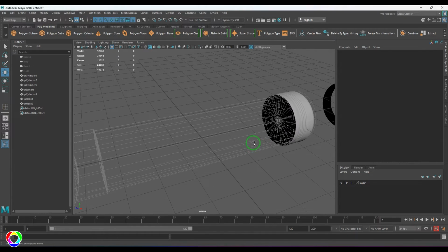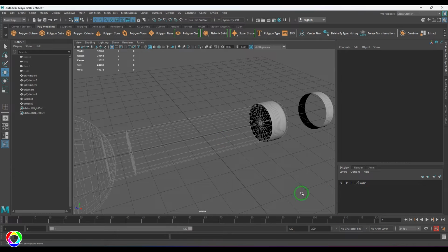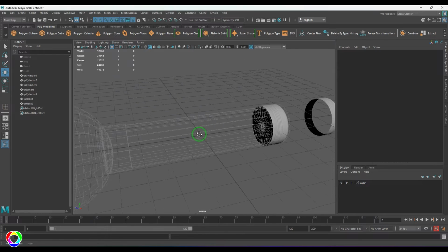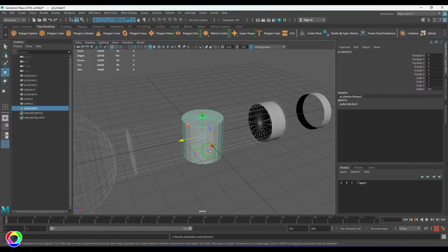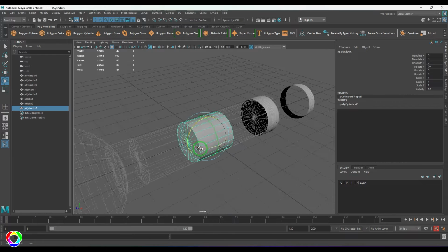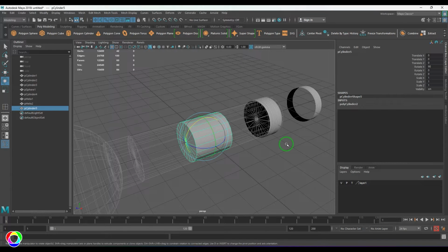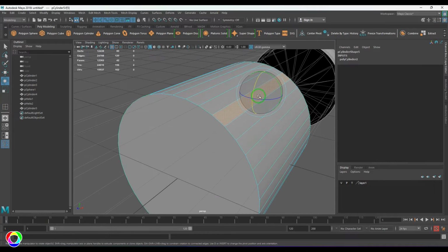I'm going to add a cylinder. So this body has some vertical strip details, so I just wanted that details to happen. So what I'm going to do is I'm going to take a cylinder, I'm going to rotate it 90 degrees, and I have got some details as I told you. So what I'm going to do is I'm going to add subdivisions of 40, and caps I'm going to switch off to 0. So after every 2 lines I've got 1 line going inside.